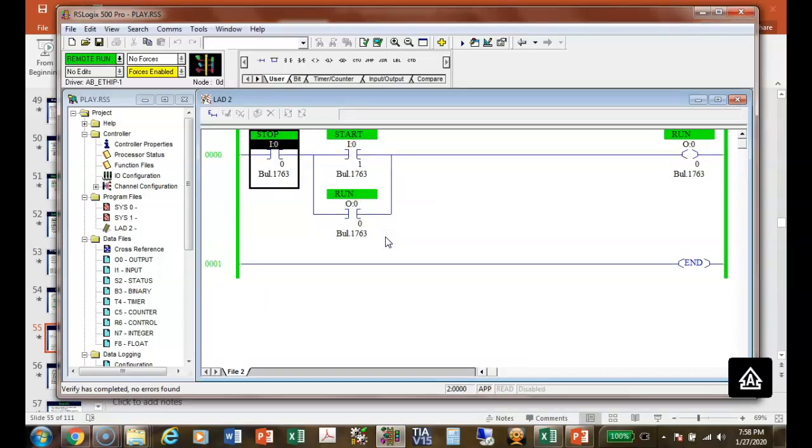Now notice automatically your 2 rungs turn what? Green, indicating this guy's up and running. So what I'm going to do is close switch 0, which is supposed to be a normally closed switch anyway, and notice it showed it what? Yeah, it showed it green, which means my signal has made it through that device. And then what's it waiting on? It's waiting on my start button, right? Everybody see this?